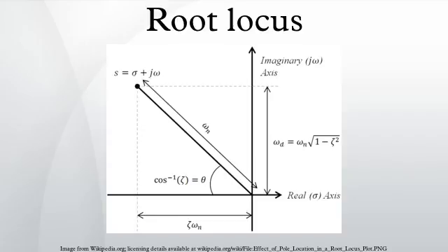A diagonal line of constant damping in the S-plane maps around a spiral in the Z-plane as it curves in toward the origin. Note also that the Nyquist aliasing criteria is expressed graphically in the Z-plane by the x-axis. The line of constant damping just described spirals indefinitely, but in sampled data systems, frequency content is aliased down